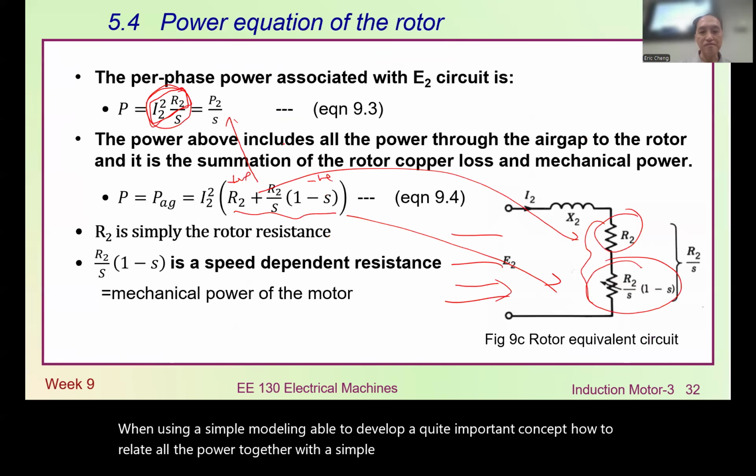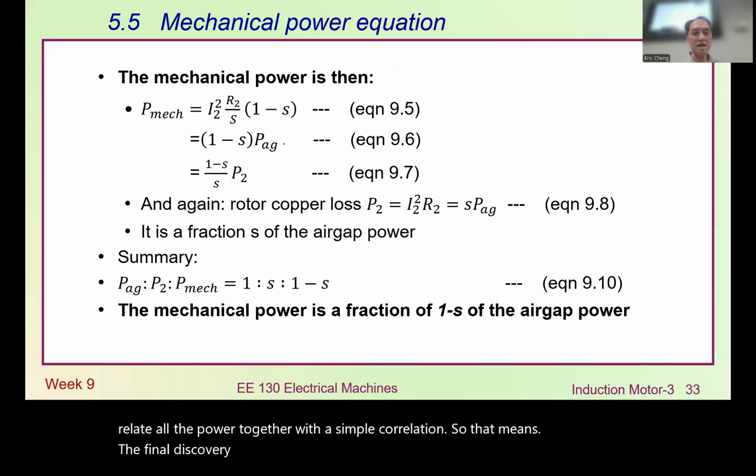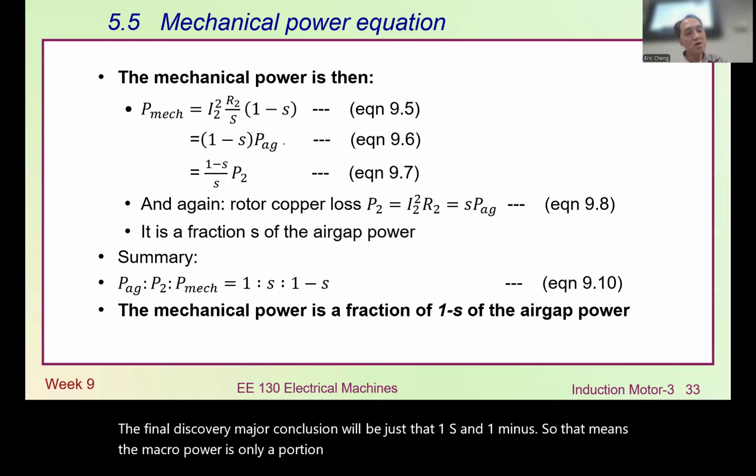The major conclusion is just S and 1 minus S. The mechanical power is only a 1 minus S portion of the air gap power.